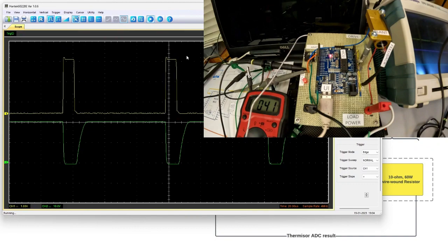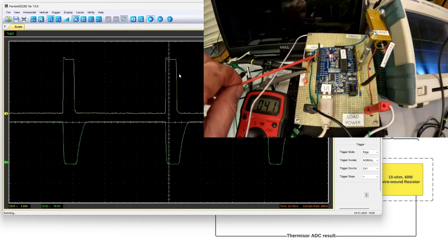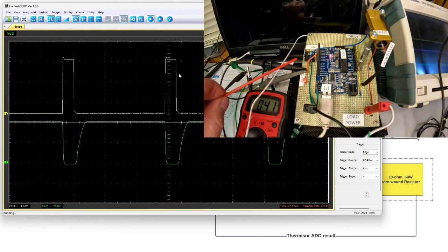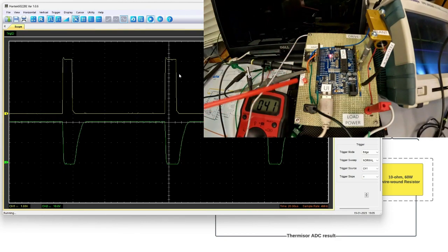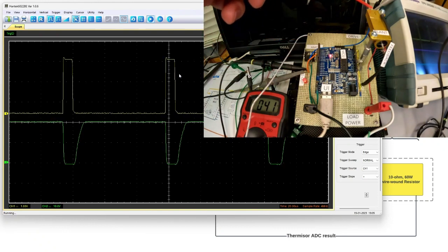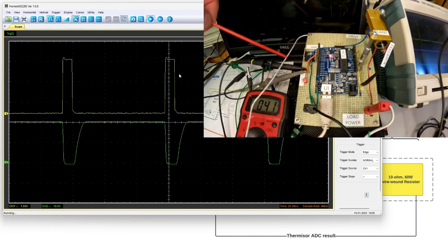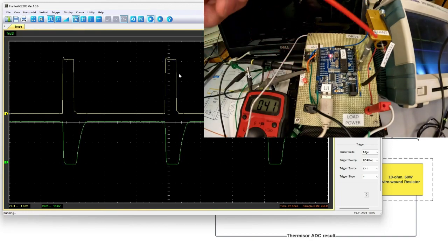This is live. So the yellow trace represents what's on the orange wire here, and that is what's closing our switch to ground and allowing current to flow through the power resistor. The green trace is on a scope probe just on the far end, on the low side, the ground side of the power resistor. That's giving us an indication, really the same information as the PWM duty cycle out, but we're able to see the high voltage power supply on that terminal.